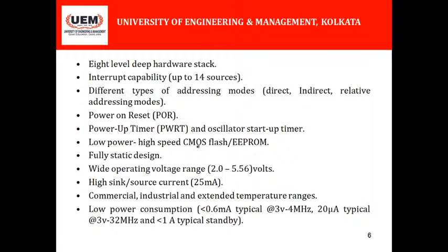Any interrupting device can request the microcontroller with the help of 14 different sources, and the microcontroller will select one of them at a point of time with the help of proper programming logic, and that particular interrupt will be accepted. The rest of the interrupts will be rejected. So interrupt capability is one of the most important features of this microcontroller.